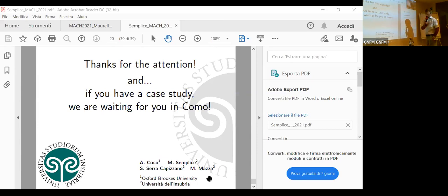Typically, when one does this level set computation, the grid is in fact some background object that is just used to store the values and to locate values in space. And therefore, typically people choose very simple grids because they are easier to handle from a computational point of view. So that's why people typically use regular Cartesian meshes.